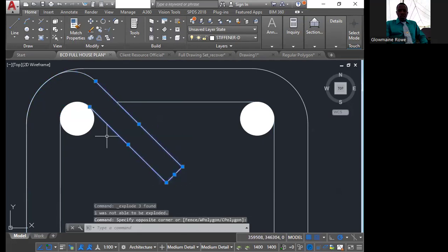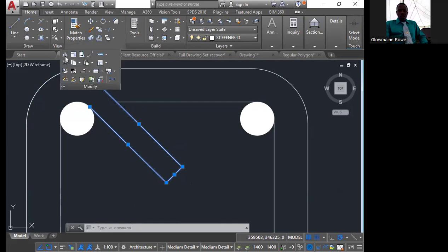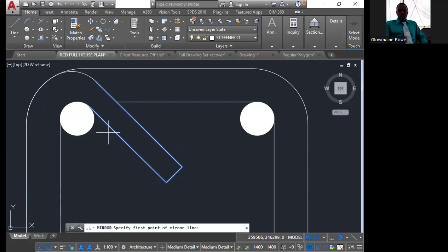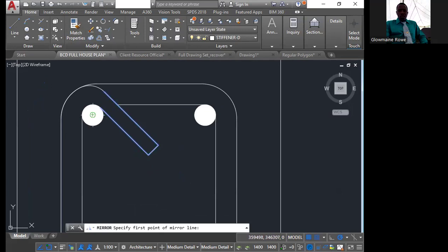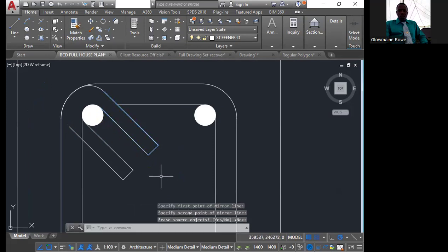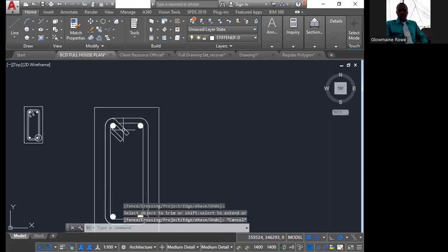Select this part here, these 3 lines, they go curve or the hook, mirror, and we're gonna mirror across a 45-degree angle. Right? So using polar tracking, see the tracking line comes up, click, press enter, and then we trim. Beautiful, beautiful. Look at that.